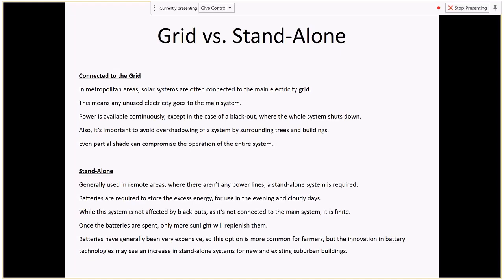So if you have a solar panel system where you do get lots of shading from trees and things like that throughout the day, it may be best to go with a system that has its own little inverters within the panels. Or if you get big blocks of sunlight throughout the whole day, we might as well go for a cheaper system that has just the one inverter on the wall, and I'll go through that. So that's grid connected photovoltaics.